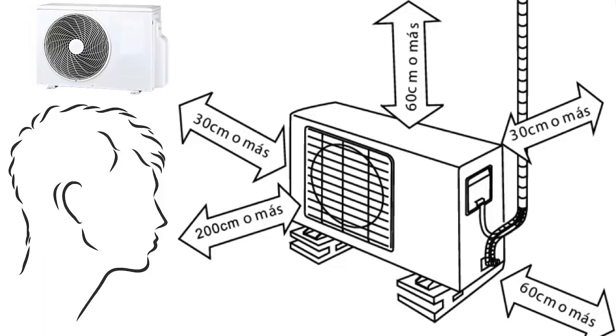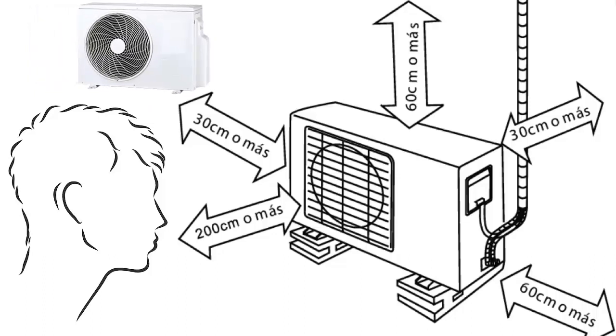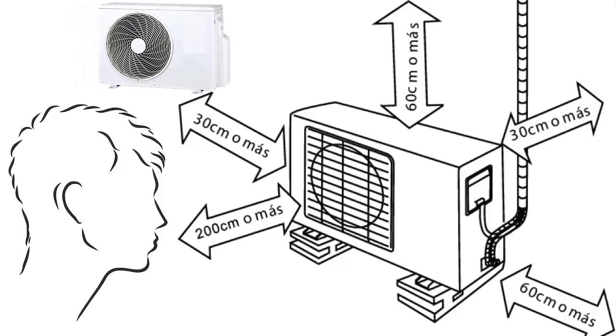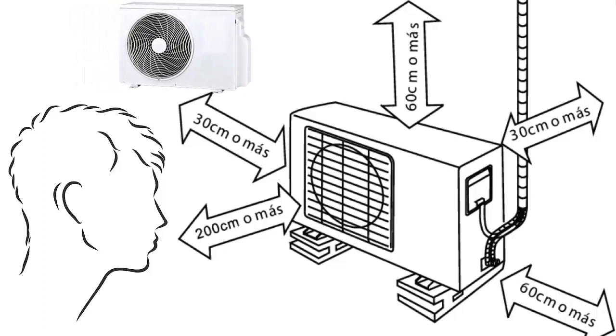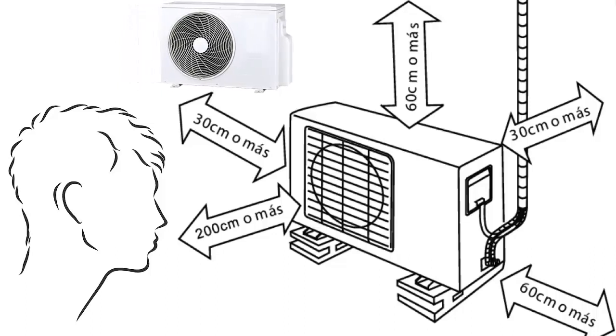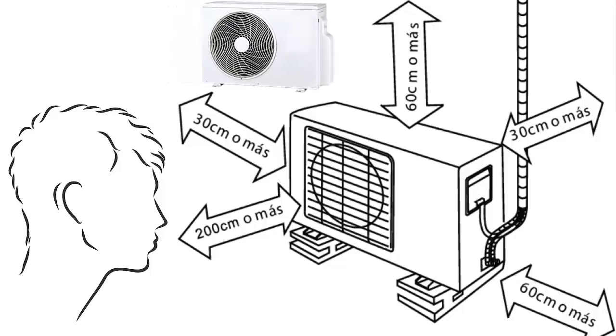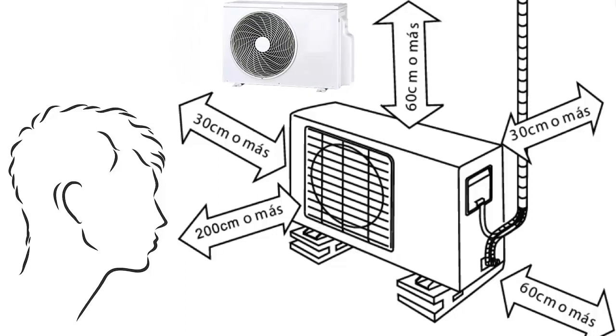Solution. A. Place the condenser unit in the coolest possible location. B. Do not obstruct the air discharges, and respect the distance between the walls. C. Airflow. Do not place it against the exterior airflow.